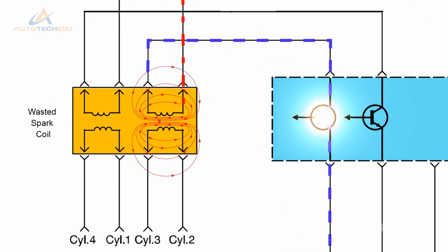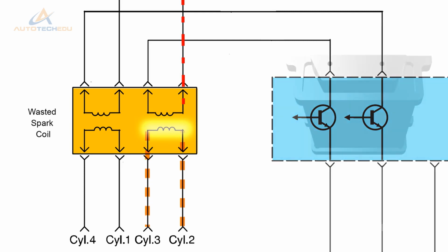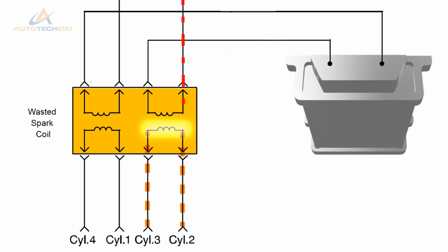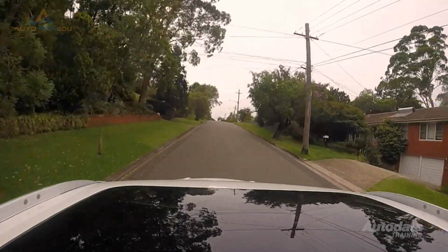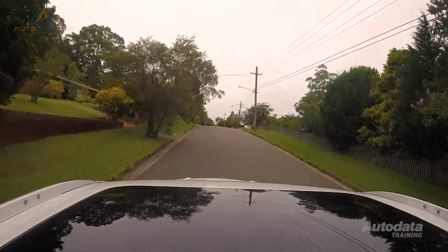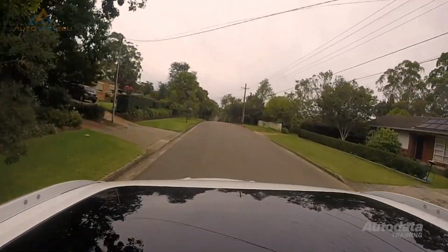When the primary current is interrupted, high voltage is induced in the secondary windings, causing current to flow in the circuit. The dwell or coil saturation time is limited by the control module. The module is programmed to only allow total coil saturation when high current is needed. This limiting prevents heat from being produced, prolonging the service life of the ignition coils. Using the inputs from the fuel management system, spark advance can be calculated to allow for all engine load conditions.